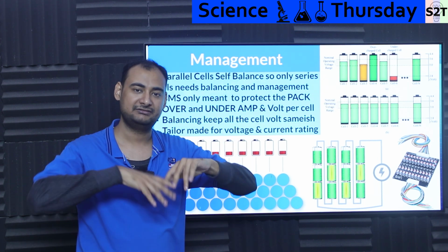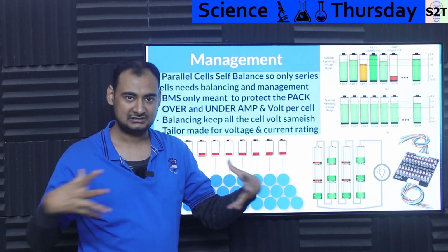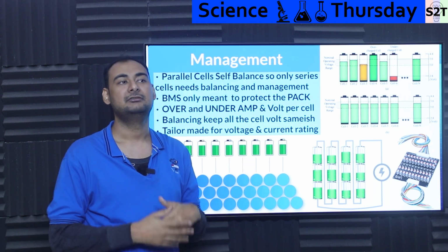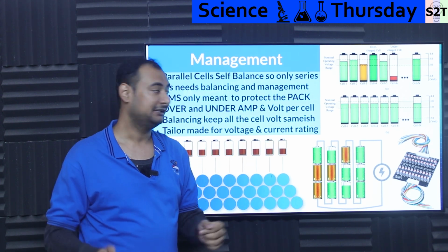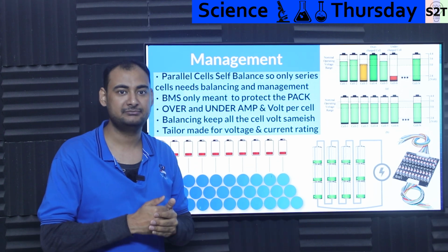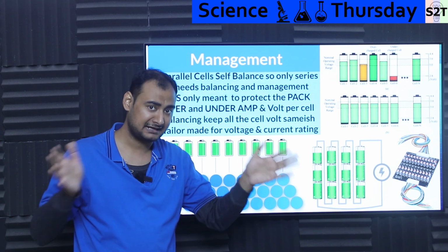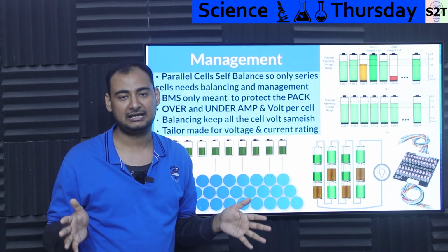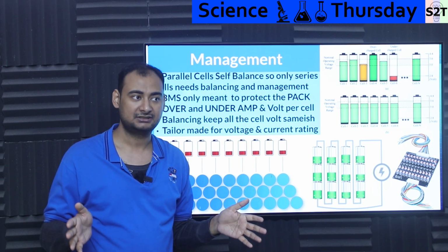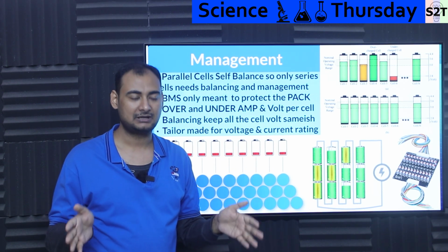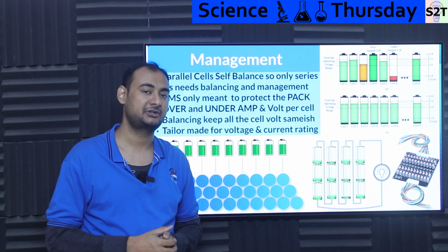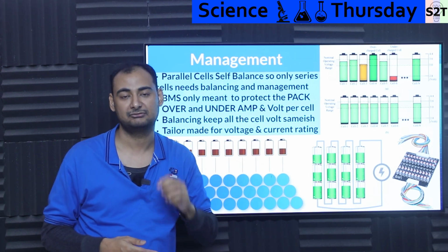And again, this is not only about BMS, it also allows all cells to be healthy enough that the drifting is not amplified. If you do not balance the cells, the drifting becomes exponentially worse, meaning a pack that could easily be 100, let's say 100 kilowatt hour, will only give you a useful capacity of 50, because the BMS will keep tripping, because some cells will get out of whack.